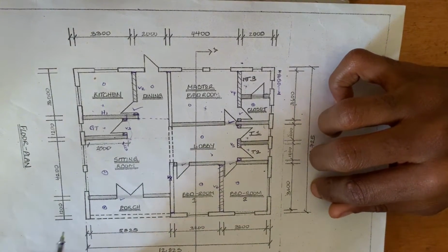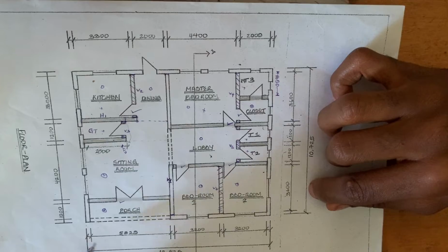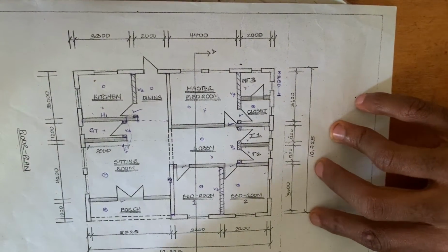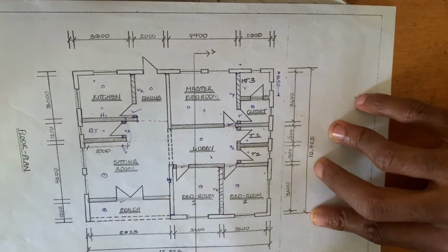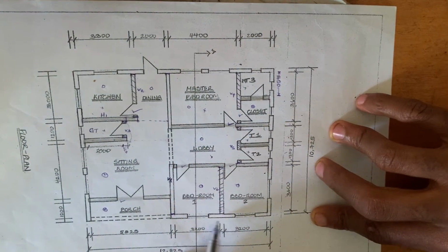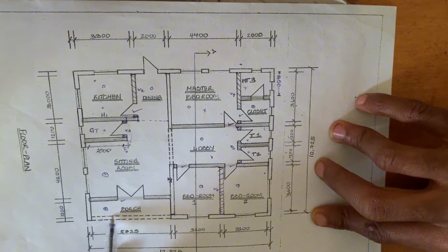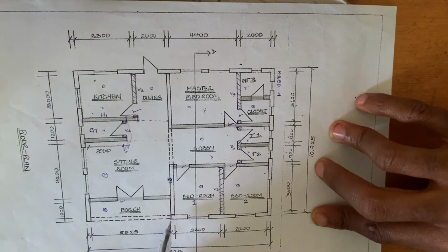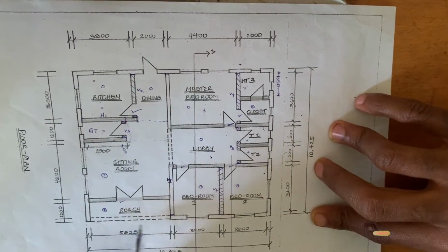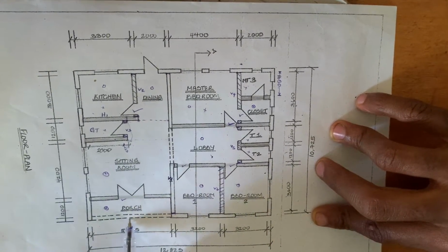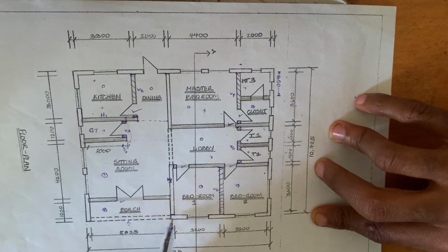Like I said in the start of the video, we are going to be calculating the block work in such a way that the block covers the entire space of the plan. Now, if you look at this plan, it is a regular rectangle. Now, block work covers round the entire space. However, there's an opening at this area. You know what dotted lines are for in floor plans. It means that there's a lintel here, and lintels are used to cover an opening. So there's an opening here for the porch where you can enter the house.